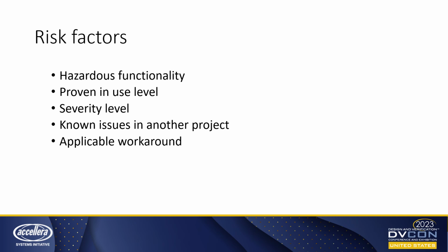The last one is applicable workaround. Workaround means that if this block is found to have critical hazard issues or systematic failures at silicon level, a backup block or backup IP located in our SoC can replace the failed IP.